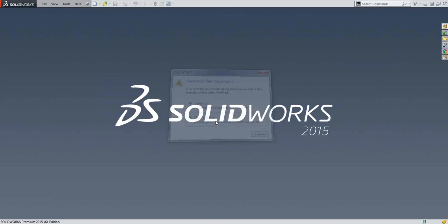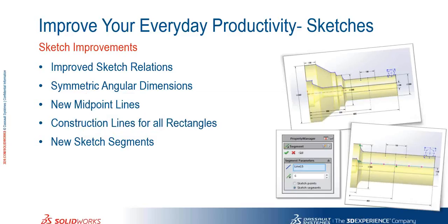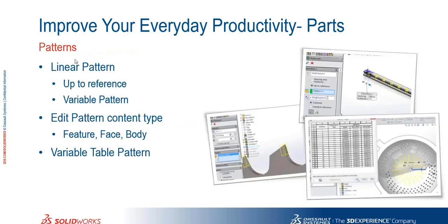So moving along, we'll go to the enhancements which have been made in terms of patterns. Now in patterns, there are a lot of enhancements. Over the period of years, we have come up with new types of patterns, like variable pattern in terms of linear pattern. Then we also have the option of editing a pattern content type with respect to features as well as face and body. And now we have a new type of pattern which is called a variable table pattern. So we'll just have a look at this.